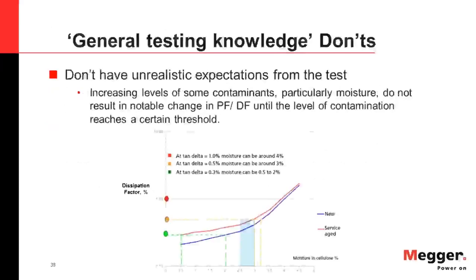And then the final don't I have in this category is don't have unrealistic expectations from this test. Increasing levels of some contaminants, particularly moisture, do not result in notable change in power factor or dissipation factor until the level of contamination reaches a certain threshold. And this figure illustrates this point.